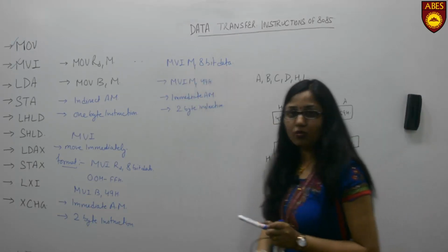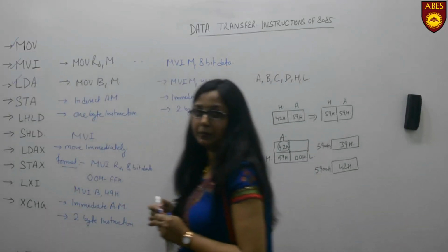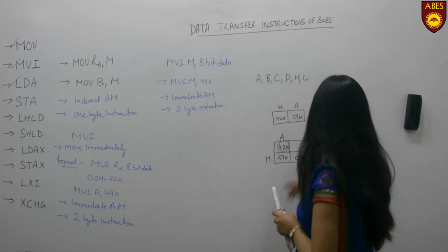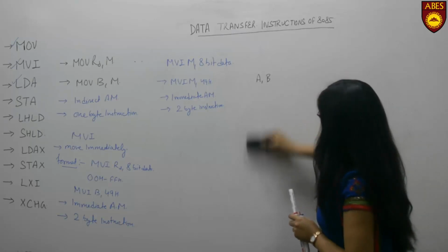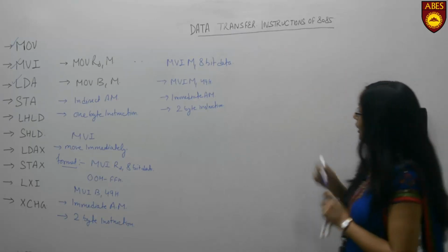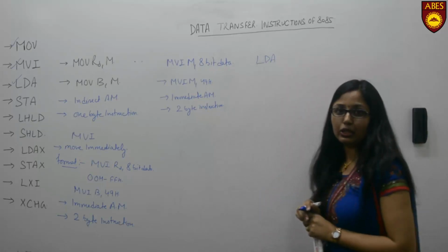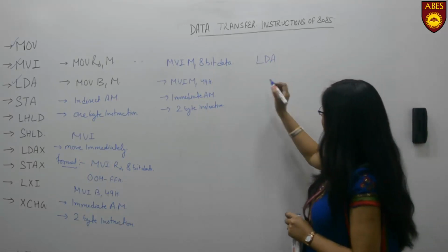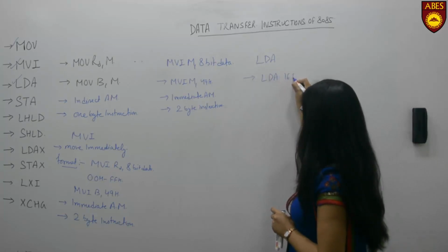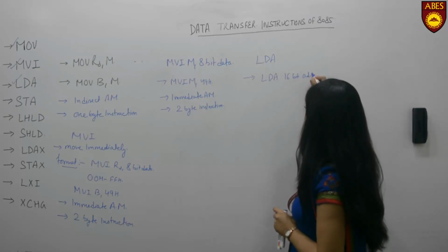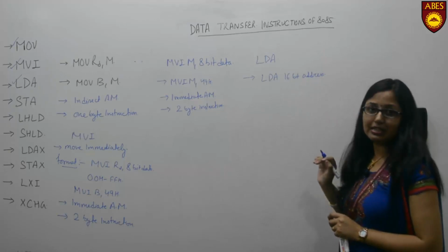Now after the move and MVI, the third instruction is LDA. LDA instruction is basically load accumulator. The format for this instruction is LDA, then 16-bit address.